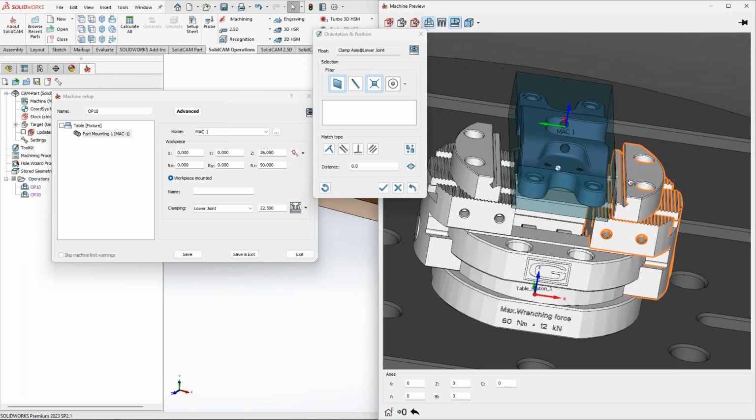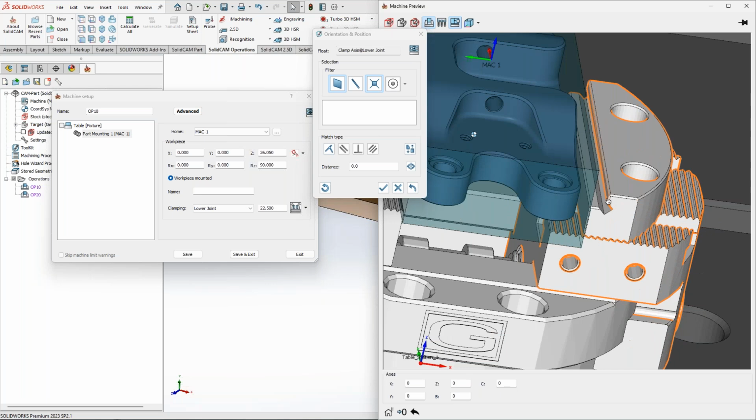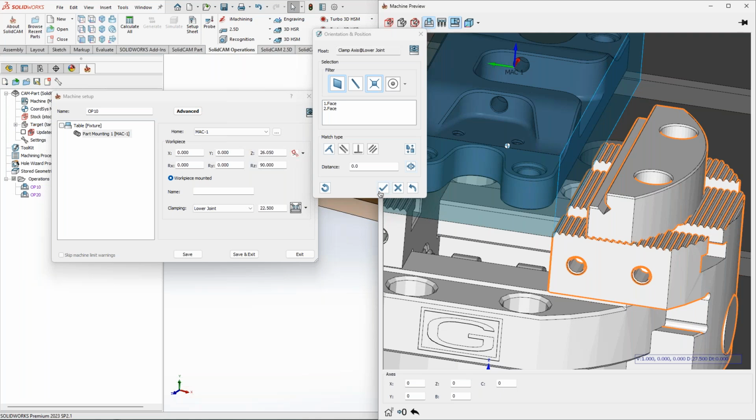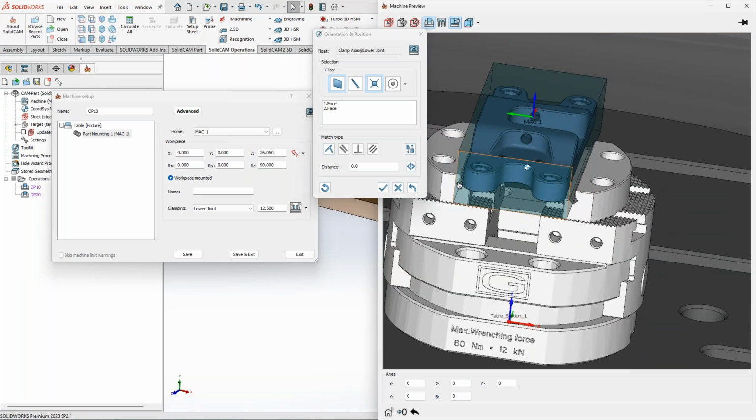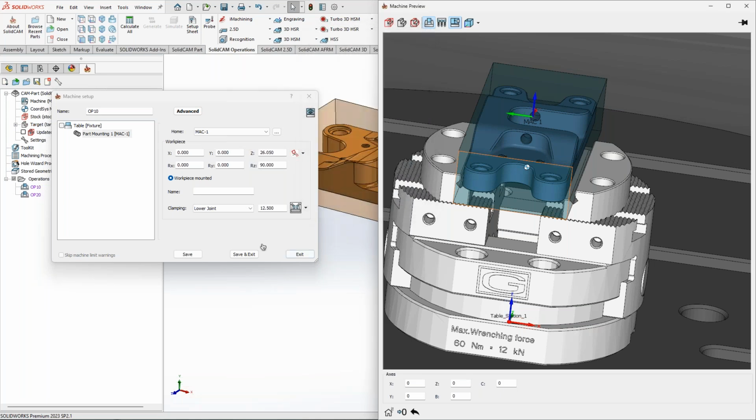And this is important to mention. So now I can just use these, just clamp, take this, take that, and just mate. There you go. If you try to do that with the other one, it will be completely ignored. I think this is very nice. This question comes very often in the support channel.